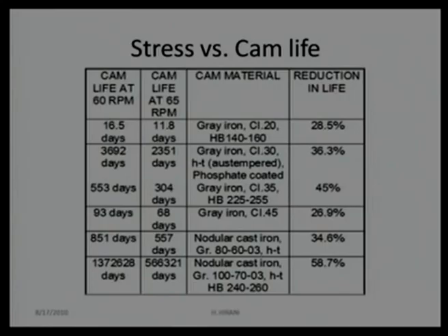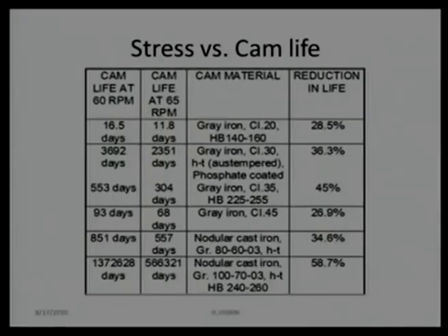However, we can provide a better lubricant, we can reduce the coefficient of friction. I have seen industry applying now two lubricants. They use high energy grade grease. After every 10 hours they re-lubricate the surface where the maximum pitting is occurring, and they use additional grease just for the circulation purpose, so that can take away the particles and lubricate those surfaces where the severe condition has not been imposed. So, those things are there.